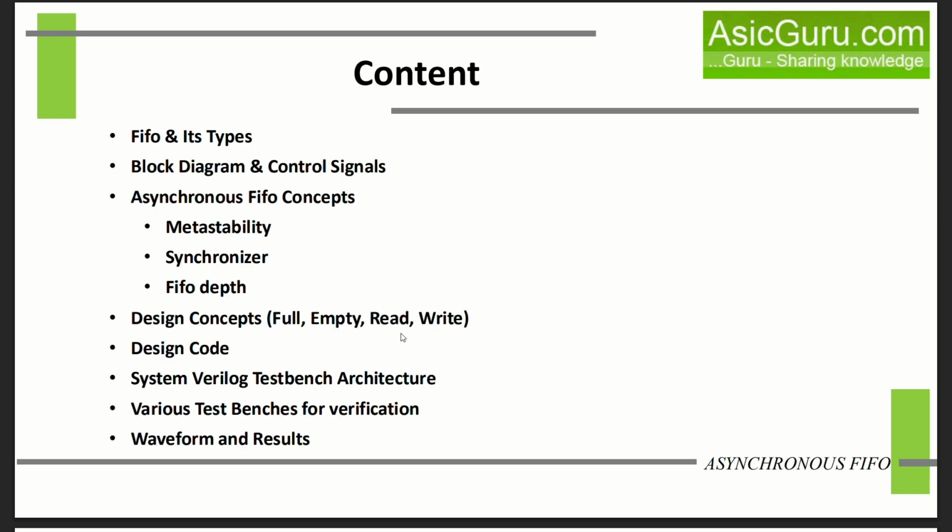First we will see FIFO and its types, then block diagram and control signals, asynchronous FIFO concepts like metastability, synchronizer, FIFO depth. Then we will see design concepts like full, empty, read and write. Then we will see the design code, then SystemVerilog testbench architecture, then various testbenches for verification, and then finally waveform and its result.